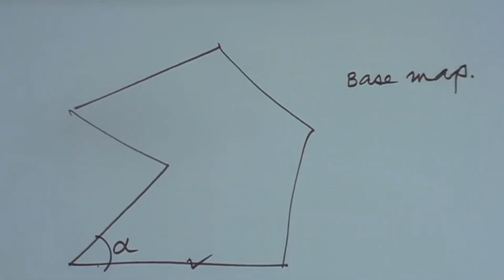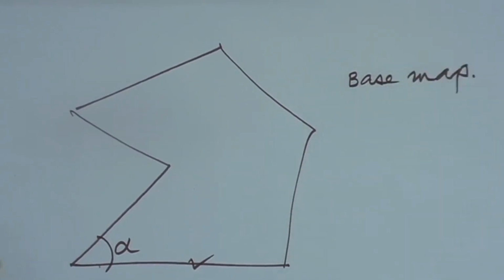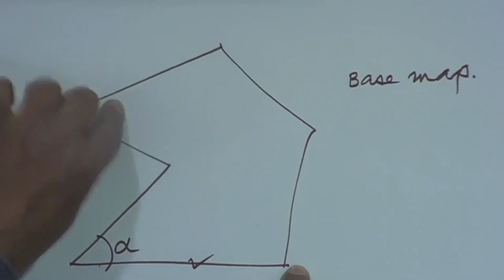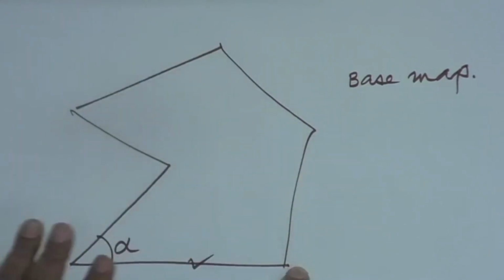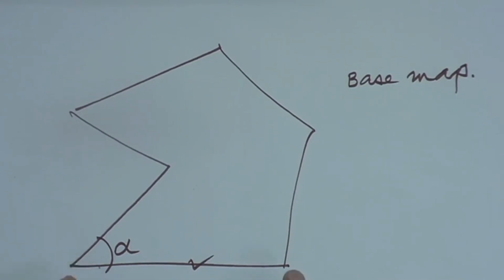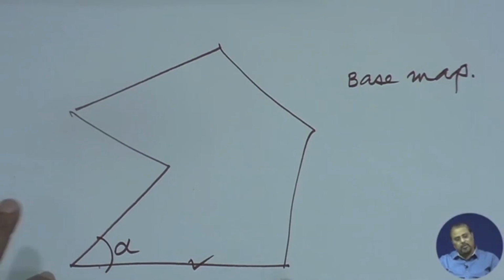Now, here your role is very important. You have to give a very clear idea to the surveyor of what he must not miss in documenting. Just as you say, this point, this traverse dimension, this length, internal angle, external angle, everything which will make a true representation in diagrams when you reproduce this. So for the base map that you are preparing, you suggest to your surveyor exactly what information he has to have.